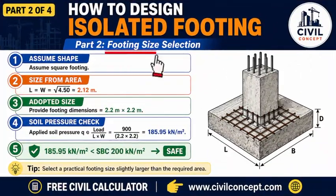Now, we select the footing size. Let us assume a square footing. For square footing, length is equal to width. So, length equals width equals square root of 4.50, that is approximately 2.12 meter. For practical construction, we adopt footing size as 2.2 meters by 2.2 meters.